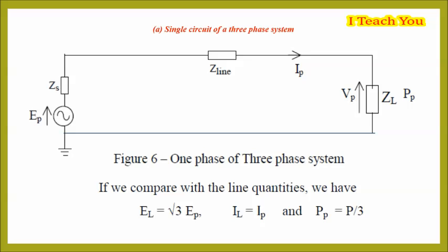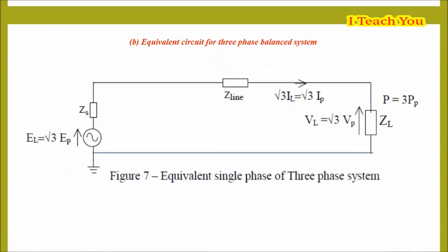Usually, we are more interested in knowing the voltage and the power from practical considerations, rather than the current. For example, if I ask you the voltage and power rating of a bulb in your home, you would know it. However, if I asked you for the current taken by the bulb, you would normally not be aware of the value but would probably obtain it from the wattage and the voltage. The same is true in a large power system. Thus we would like to reformulate the problem so as to give the voltage and the power at the desired values, even at the expense of a wrong current.